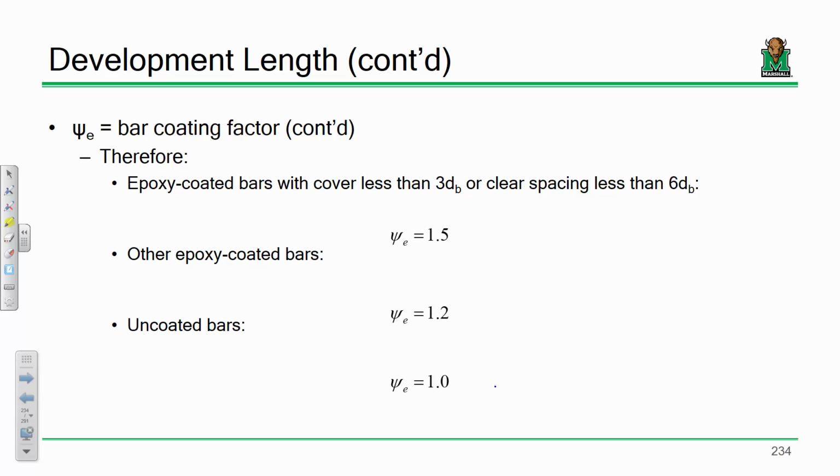One thing that you could use is galvanized rebar. You actually take the bar and just hot dip galvanize it. Now, it's a little more expensive, but it pretty much has the same surface conditions as epoxy-coated bar, so you can take your ACI factor to be 1. So that might be an option.